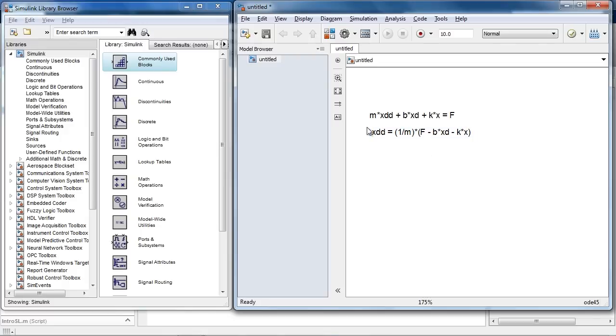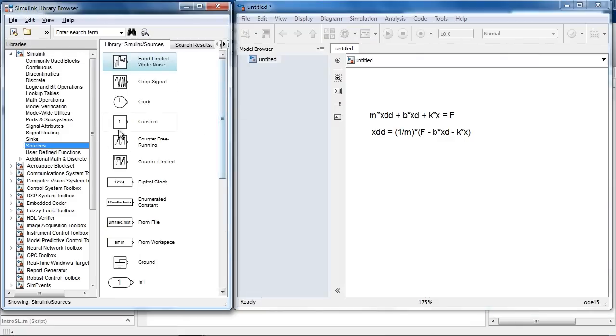So all I've done here, Michael, is I've written out the equation for a mass spring damper where you have the mass, damping coefficient times the velocity, and the spring constant times the position, and then you have a force to drive the system. Yep. And I've just moved some of those pieces around so that this is actually going to make it a little easier for me to design in Simulink. Okay, so just an algebraic manipulation of the first equations.